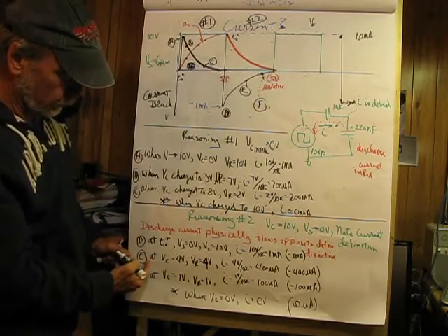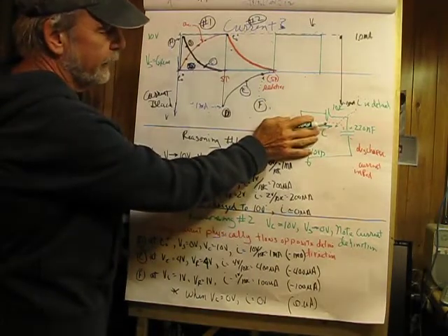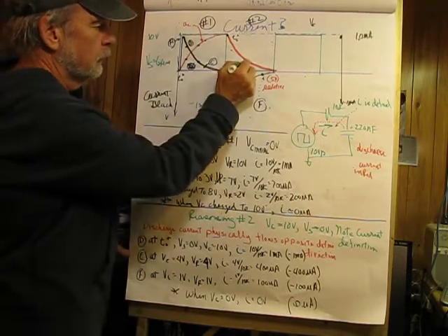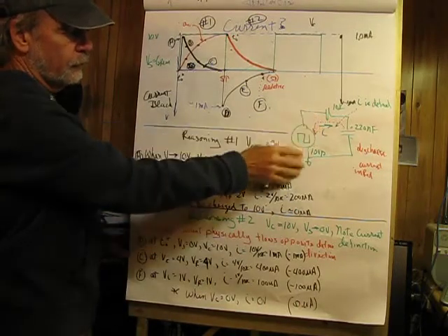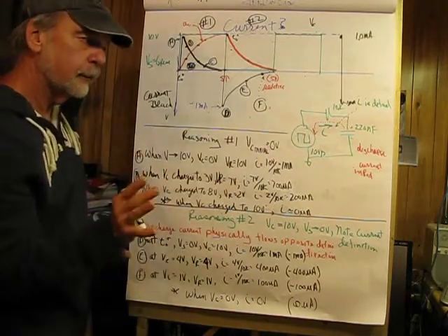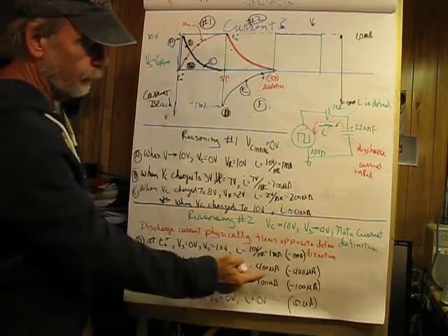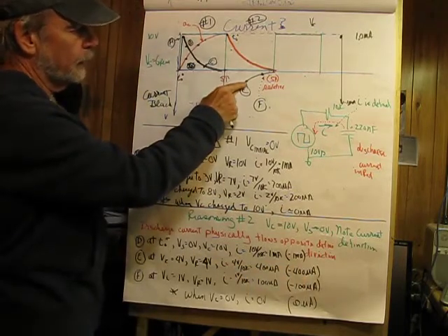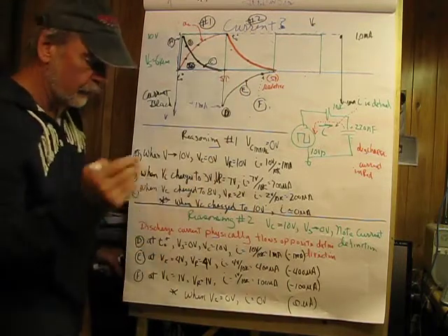Another example, as we work through this, at VC equals 4 volts. Now, the capacitor has decayed to 4 volts, which would be maybe here. What would the current be? Well, the voltage across the capacitor is the same as the voltage across the resistor. This is a short. I'm going to keep saying that. Internal impedance 0 ohms. I'm going to keep saying that too. So I would be equal to 4 volts divided by 10K, 400 microamperes, and then I'm going to put that as a negative 400 microamperes, which would be right here, corresponding to 4 volts on VC.